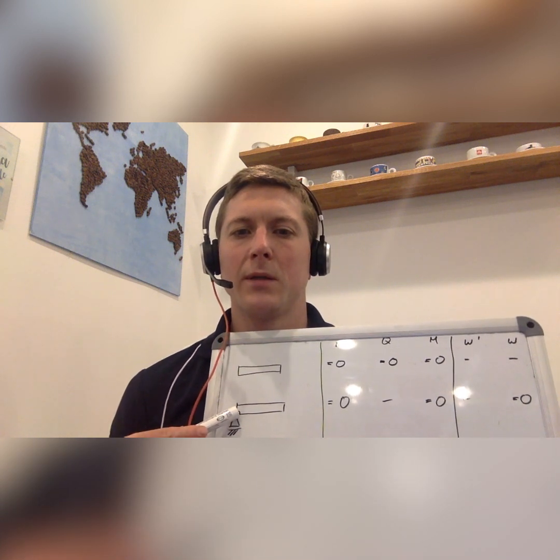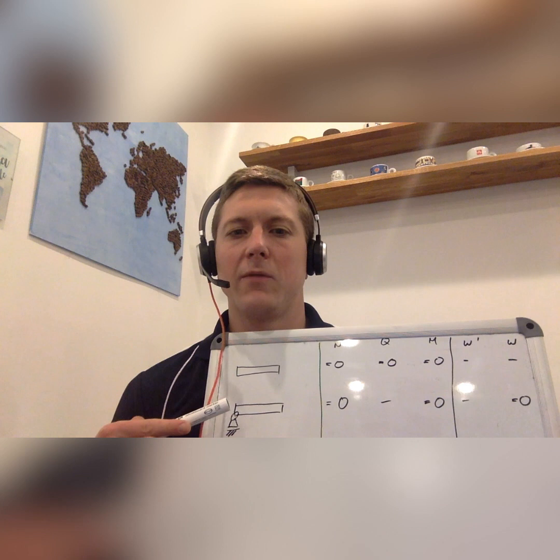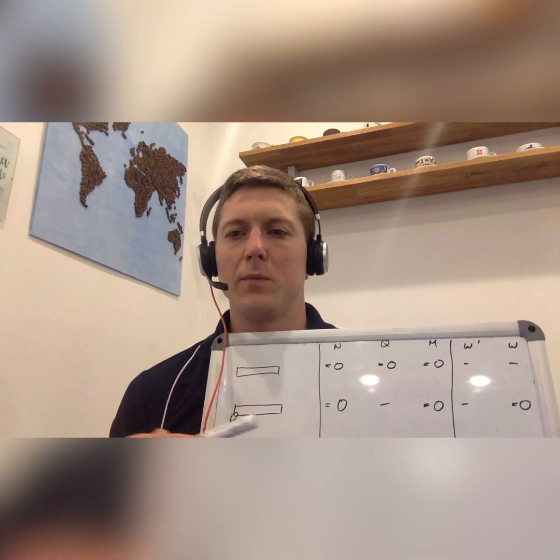Let's look at this point here. This bearing point, as already mentioned, prevents the point from moving upwards or downwards, and this movement is described by this w, so this w has to be 0. The point stays at this c position. But of course, it is possible that there is a deflection of our beam in this position, and that would mean that we cannot say anything on the derivative of the deflection.